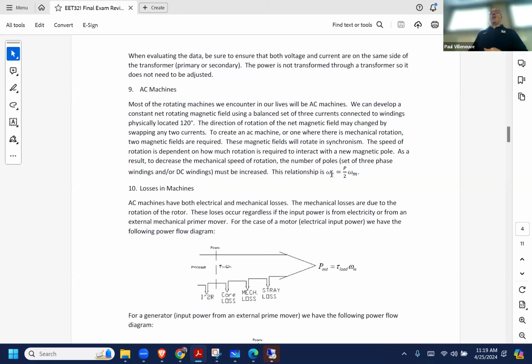And what we saw is when we ran through our sine wave, as we, quote unquote, rotated through our sine wave, which is just another way to say time has elapsed, we saw that our magnetic field rotated. And if it was a three-phase machine, we saw that the magnetic field rotated, but its magnitude never changed. It was always at 1.5 times the magnitude of any maximum individual phase. So it was constant, which is what we want because that gives us a chance of constant torque.